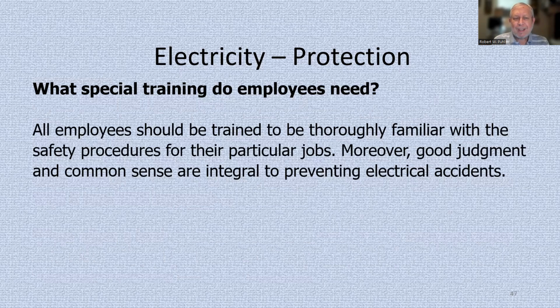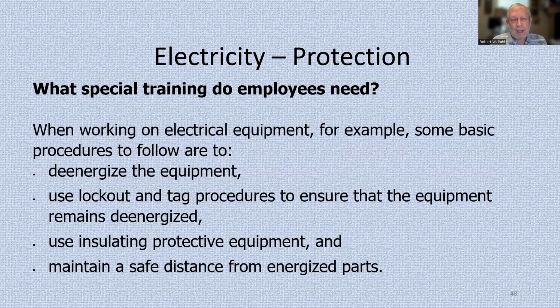What special training do employees need? All employees should be trained to be thoroughly familiar with the safety procedures for their particular jobs. Moreover, good judgment and common sense are integral to preventing electrical accidents. Yeah, good judgment and common sense can prevent a lot of accidents, as you'll probably find out in your career. When working on electrical equipment, for example, some basic procedures to follow are to de-energize the equipment. Makes sense. Use lockout and tagout procedures to ensure that the equipment remains de-energized. Use insulating protective equipment and maintain a safe distance from energized parts.